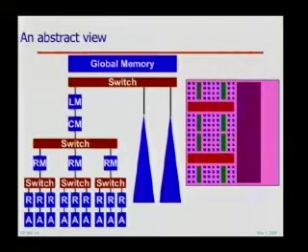And so the view of the machine from an abstract point of view is a tree. At the bottom level of the tree, we have these floating point units. Right next to every floating point unit, again part of the blue dot, we have register files dedicated to that floating point unit. And then we have various levels of switching and the next level of memory, a regional memory, a chip memory, local memory off chip, and then finally global memory anywhere in the machine.